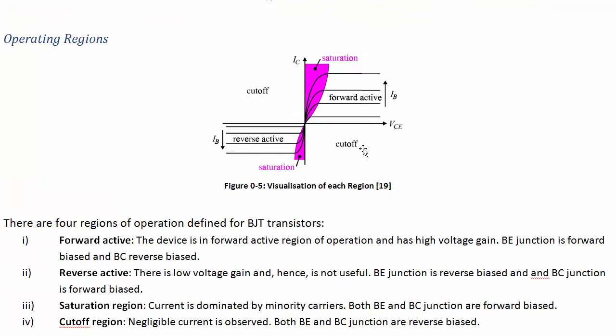All right, so the operating regions, just to summarize that, we've got the forward active region, what we've just been calling the active region, and then the saturation region if you increase the base voltage too much, to the point where the collector current is not just a constant with collector emitter voltage. Now, you could also just reverse all of the flows and get current flowing in the opposite direction.